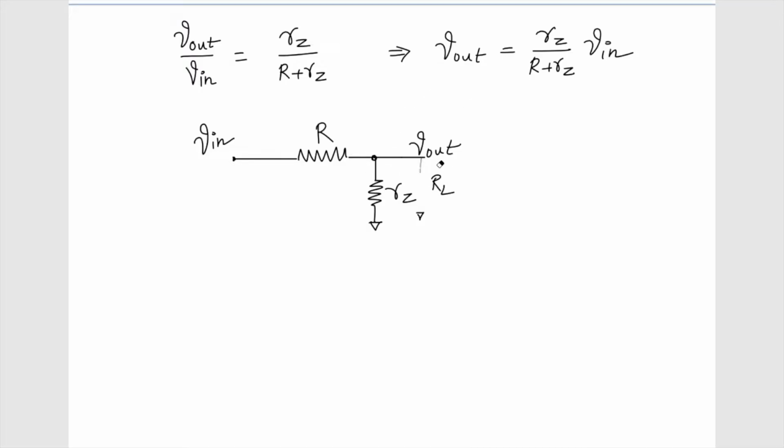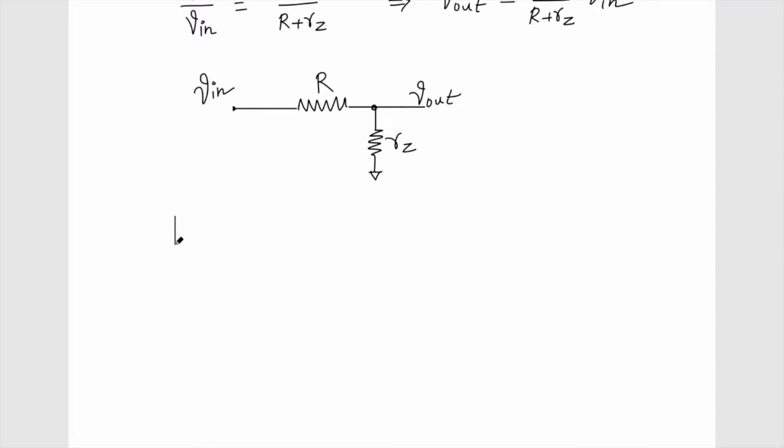So the conclusion here is that if I have any DC voltage, something like this, VDC, in a small signal analysis, it will get just shorted, okay? Why? The reason is because when we do the differentiation, this DC voltage becomes 0, right? Anything constant becomes 0.